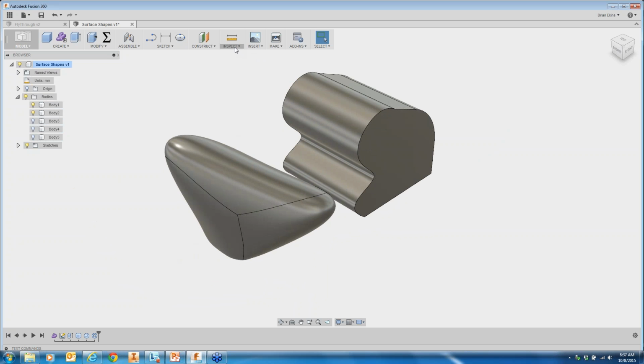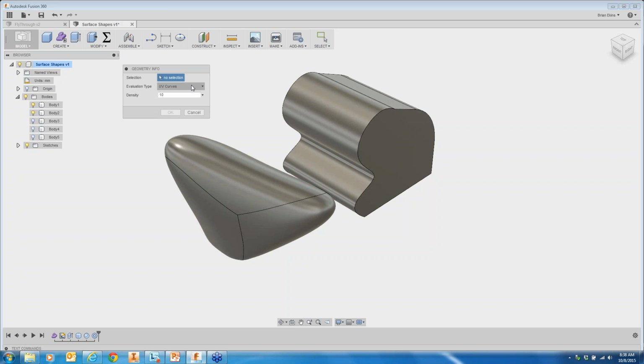And so I've written a little add-in. And one of the things it does is it'll draw that grid on the face. So what this does is, it has me select a face, and then the program is getting that selection. It's getting the surface evaluator from that face, and then one of the things that surface evaluator does is it says, okay, give me the minimum.